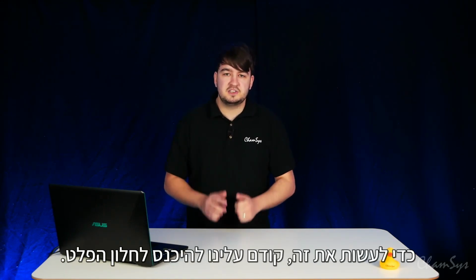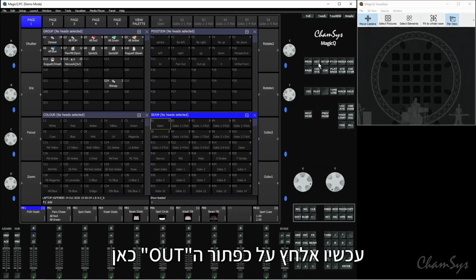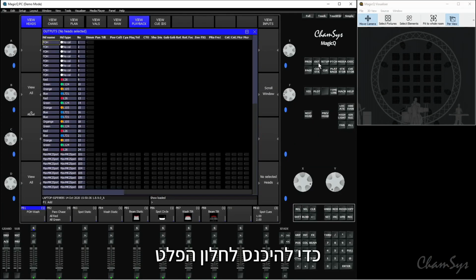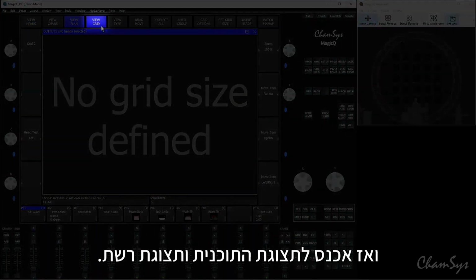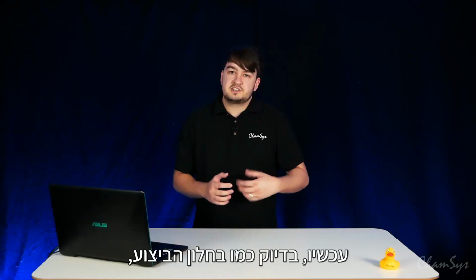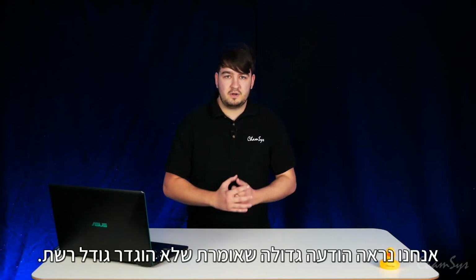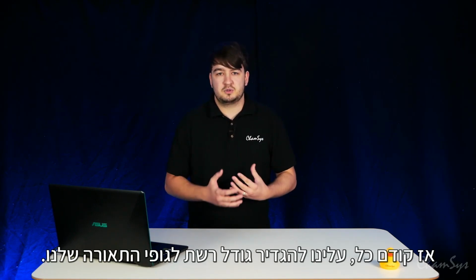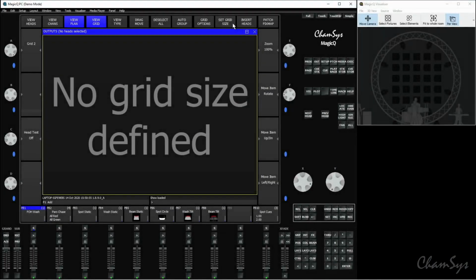So to do this, we first need to go to the output window. So if I press the Alt key here to get to the output window and then go View Plan and View Grid. Now, just like the execute window, we're now going to see a big message pop up saying no grid size defined. So first of all, we need to set up the grid size for our fixtures. So to do this, I'd go set grid size at the top here.